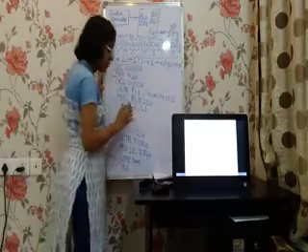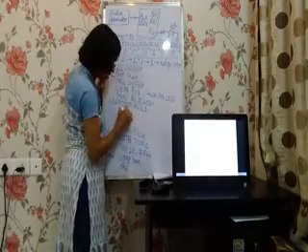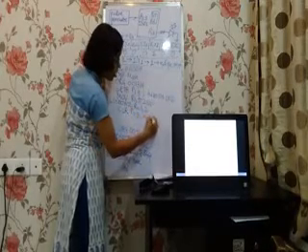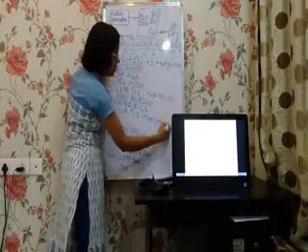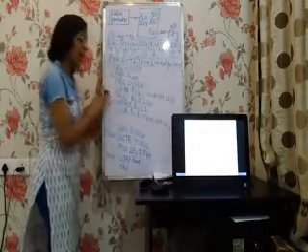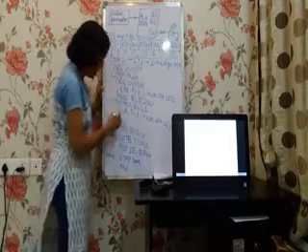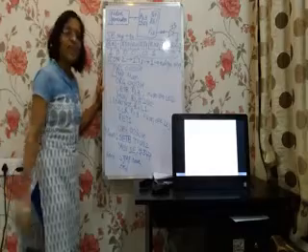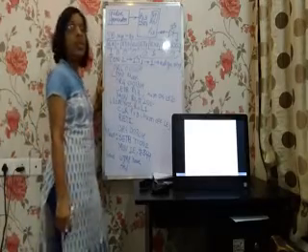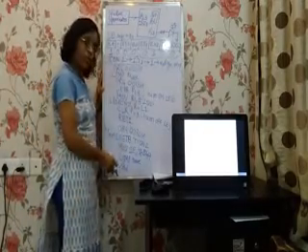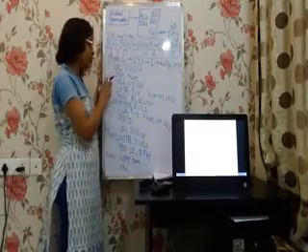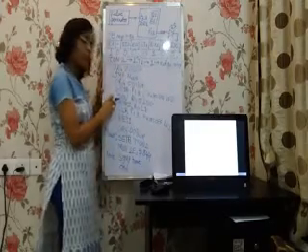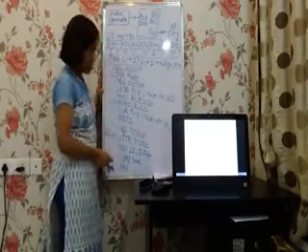So let it remain on, and then what do I have to do? I have to clear P1.3 to turn off the LED. The LED has to be turned on, wait, and then turned off. And then RETI. So whenever there is a high to low transition on the INT1 pin, the microcontroller will be interrupted. It will go to the address 13H, turn on the LED here, wait for some time, turn off the LED and come back to the main program.